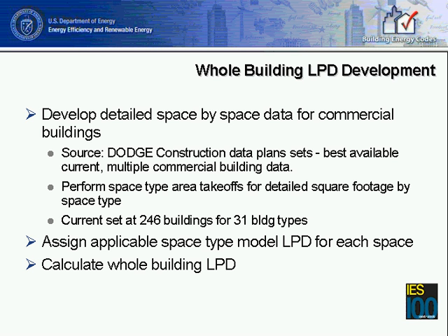A Dodge Construction database set of plans was used. Individual space takeoffs were done on these buildings. The current set is at 246 buildings, which makes up the database for developing these values. So it's based on some actual real building data. What happens is you assign these space-by-space LPDs to these square footages and calculate a whole building LPD.